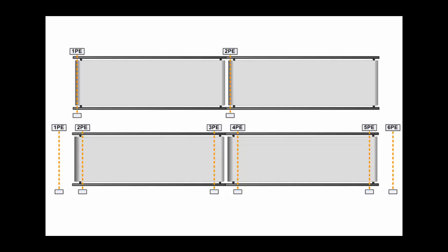When you only have 2 photo eyes, sometimes you end up using timers to simulate sensors. For instance, if you know that the conveyor belt moves 1 foot per second and your cartons are 12 inches long, then you know that for roughly every 1 second, the carton will travel 1 foot down the conveyor. So if you have a 10-foot conveyor and you see the photo eye blocked and then cleared and the conveyor motor is still running, you can use a timer to determine where the carton is at on that conveyor. With more photo eyes, that becomes less necessary.